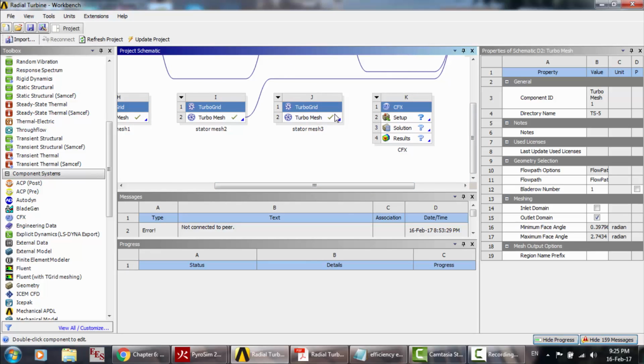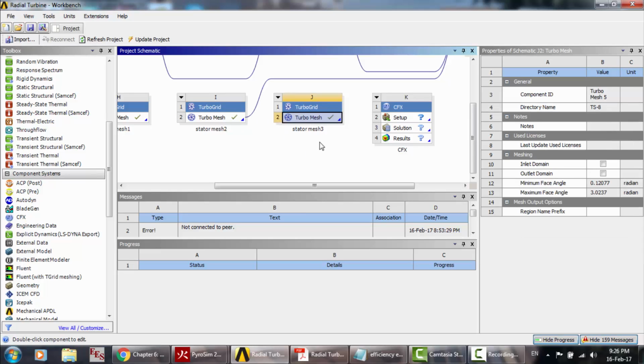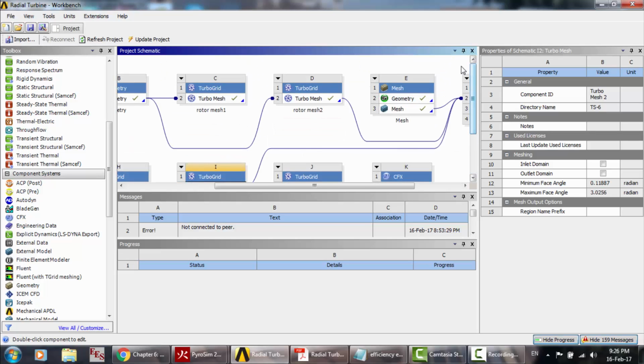Notice that I have here 3 standard mesh sizes. I decreased the wall distance to a limit that this mesh is very low in size. Okay, the wall distance is very low, and this causes instability of the simulation. So you have to know what is the optimum mesh size. It is not good to decrease it. No. Here the rotor.